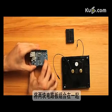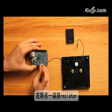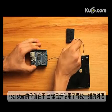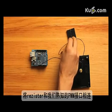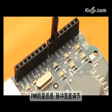Attach the Ethernet shield, connect the negative terminal of the meter to the ground, and the positive lead to a resistor. The value of the resistor you use depends on what meter you're using. For a 0 to 1 milliamp meter, like the one I have here, use a 4.7K resistor. The resistor connects to a PWM pin on the Arduino. The PWM pins are marked with an asterisk on the Ethernet shield.